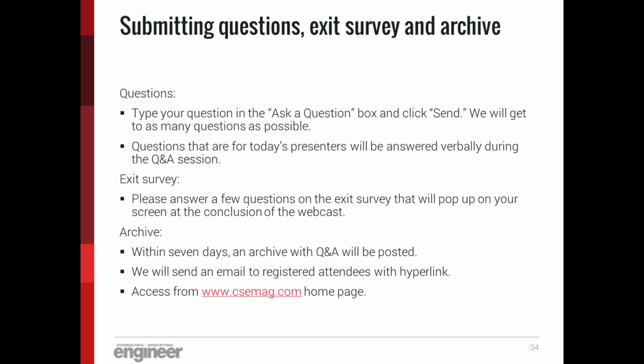Okay, so basically the codes, for example, the Life Safety Code has 2 chapters that invoke NFPA 110. And in at least one of those chapters, it talks about how many hours the generator needs to operate for that particular type of load, which I believe was the means of egress. That's the emergency lighting for the means of egress.